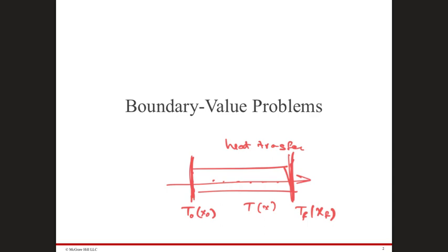And assuming that the source of your cold air is coming from those slots, with a particular temperature, tell me how it will look at different locations of the room, maybe after a certain time duration, or even as a function of space and time as well, right? So typically you are trying to solve this problem with boundary conditions, not really with initial conditions, okay? That's the whole idea of boundary conditions.